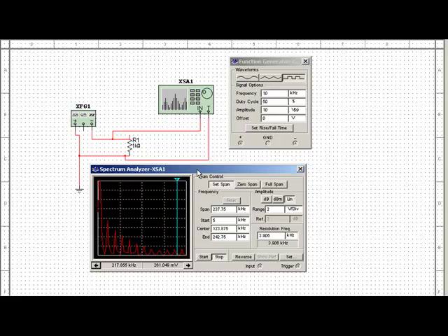harmonics, and here I have a circuit set up, and this is a function generator, and we're generating a square wave at 10 kilohertz, and the amplitude is 10 volts peak to peak, and that signal is put across this resistor right here. And the spectrum analyzer is set up across this resistor, and we're looking at the output that the spectrum analyzer displays. It doesn't instantly display. I had to go in and set all this stuff up. I'm not going to go into that because we're not going to be doing that, but I did want to show you the final outcome.